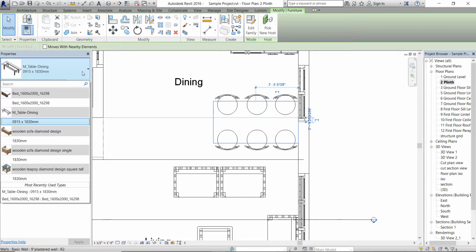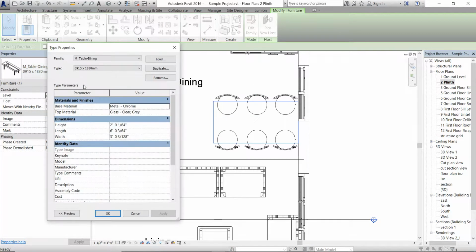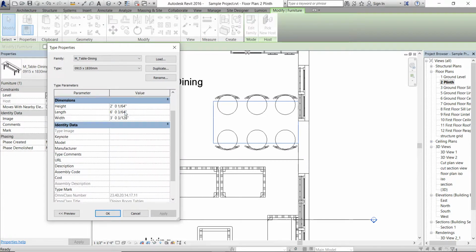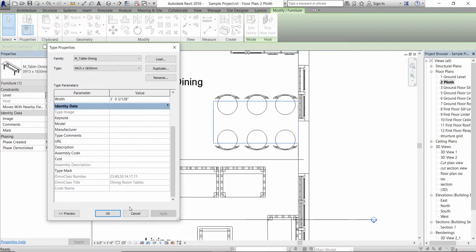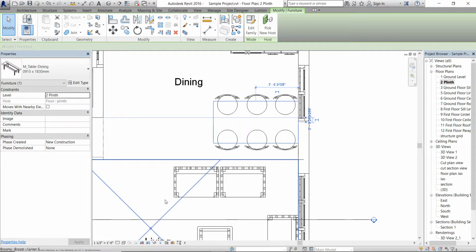Revit provides controls for how elements are constructed and located in a project using the family, type, and instance properties dialog boxes. The family properties control the geometry, the type properties control the size, and the instance properties control the location in space. Thus a Revit architecture project is built upon by Revit elements and families.